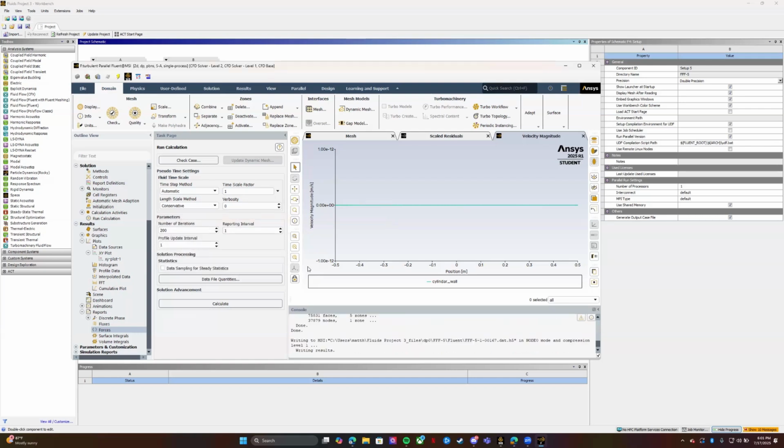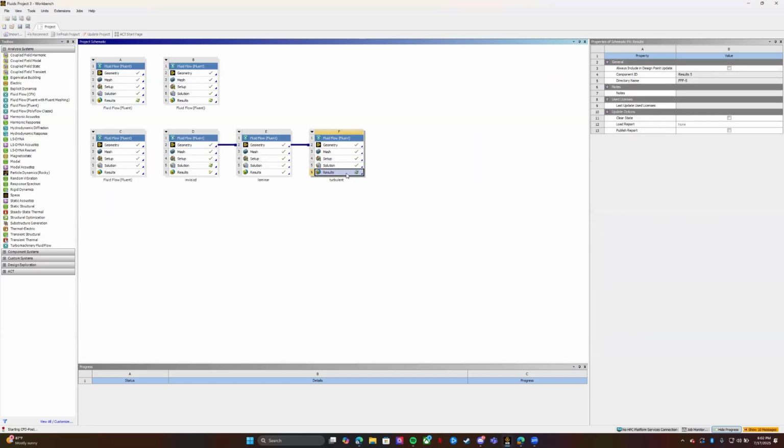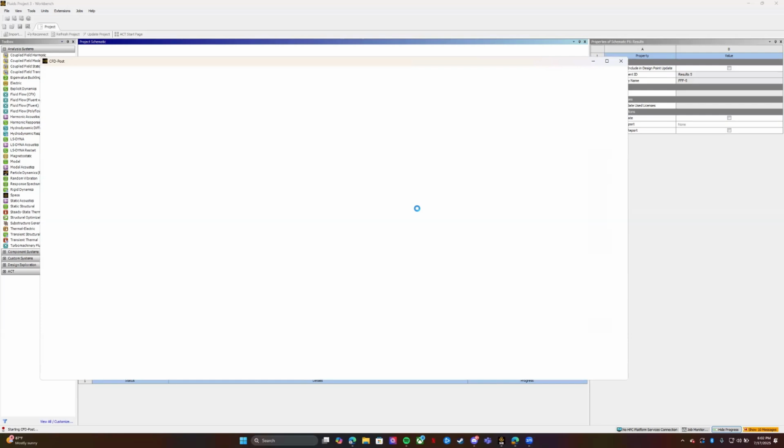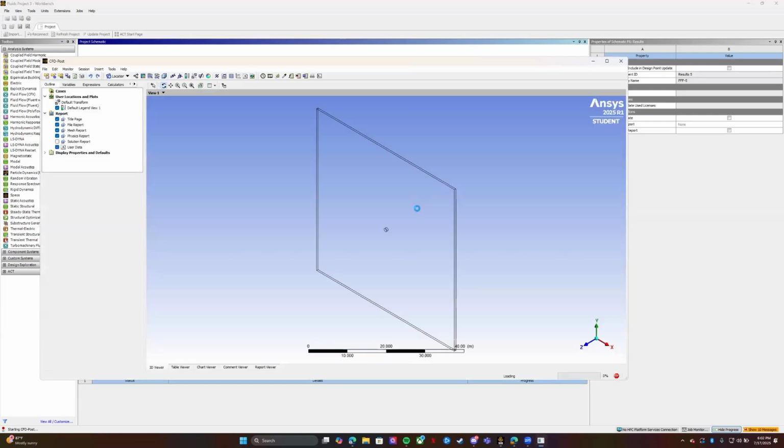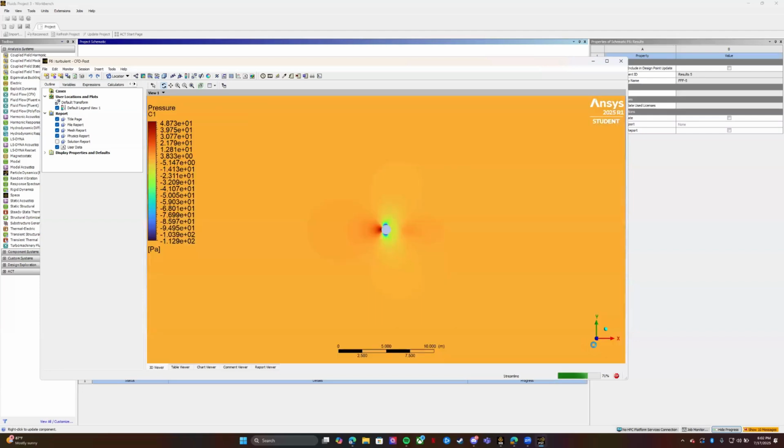And we can go to our results tab, and we can see the difference in our contours and streamline. Like before mentioned, with all those graphs, you would write to file to get the data from there so that we can compare them between all three cases. So as you can see with our contour here, for our pressure, we're going to see a maximum here. We're not going to see it in the back because we're going to have that wake region, but we're also going to see it kind of smooth out towards the top in terms of pressure.